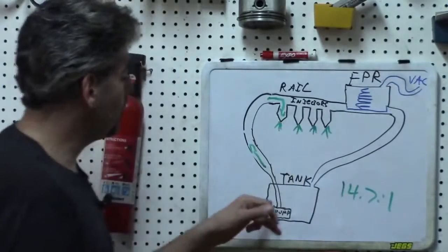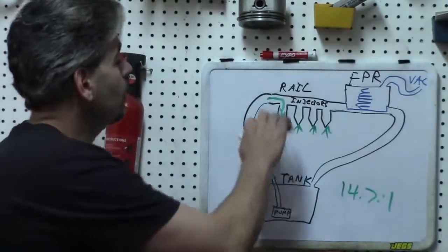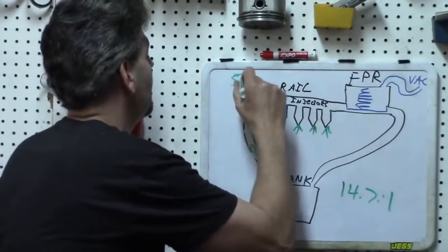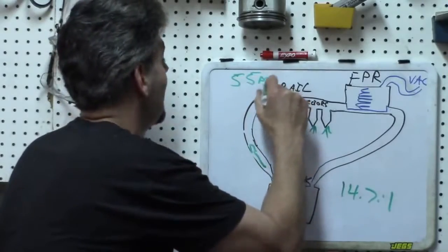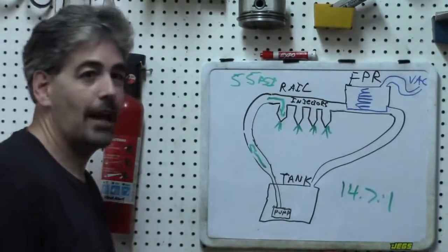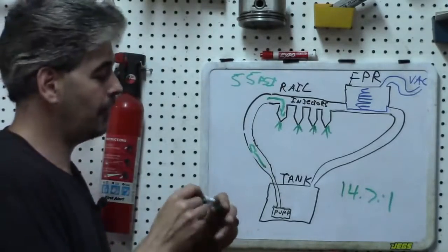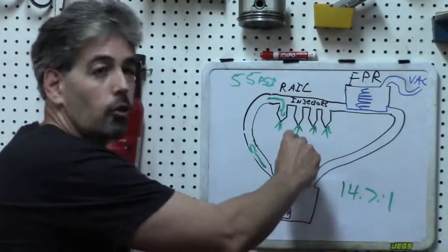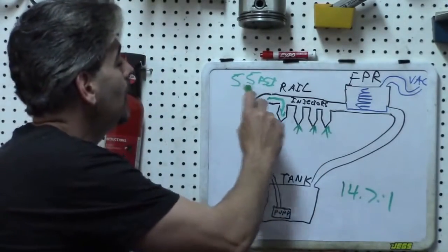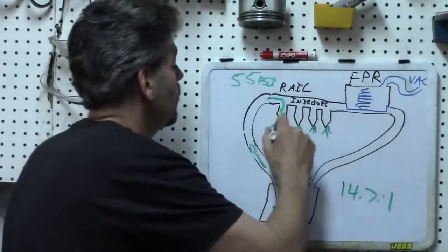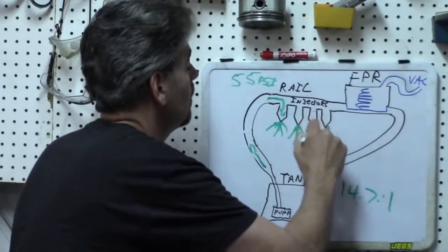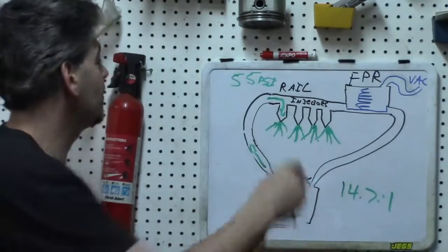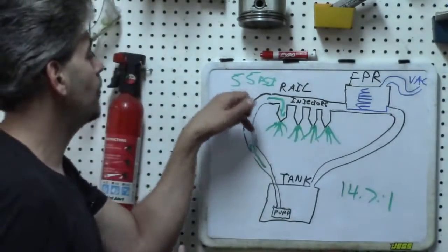If the fuel pump is delivering fuel, and there's of course going to have to be some pressure here, and let's say the pressure is a typical 55 psi, and that fuel runs out of the injectors. Hopefully you have enough of a conceptual idea of this that you would see that by opening the injectors longer, it would drop the fuel pressure in the rail because we have more fuel coming through the injectors, which of course would be like releasing your thumb off the end of a hose and dropping this fuel pressure.